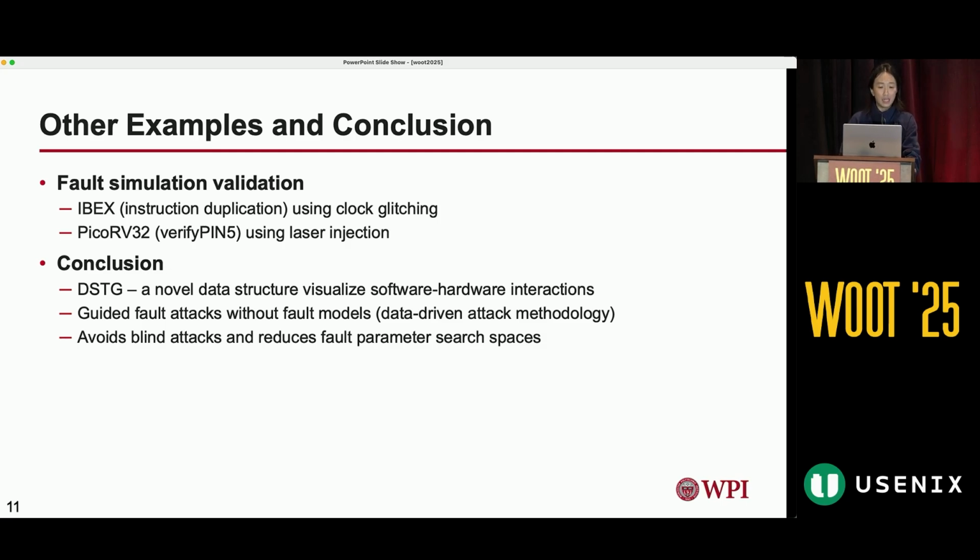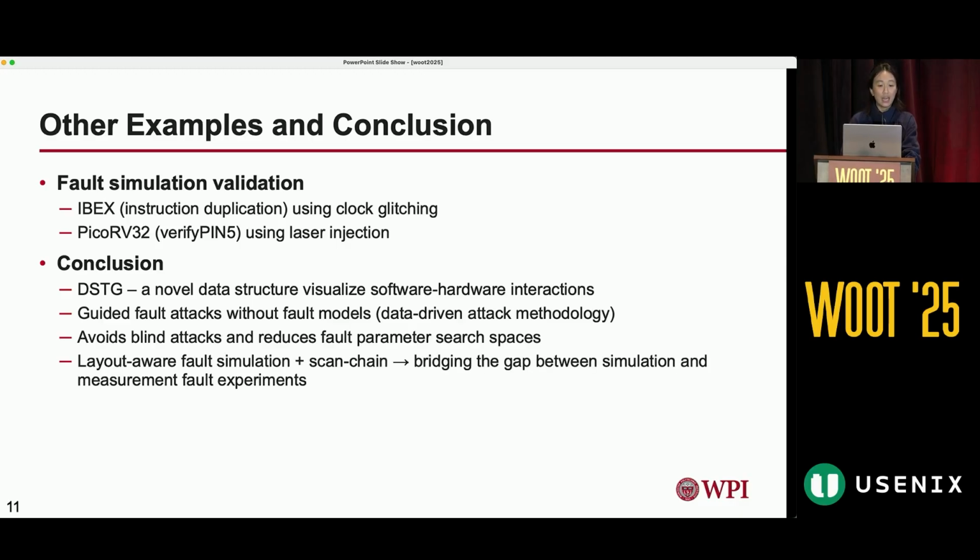By having this guided attack, we avoid blind attacks and are able to have very high precision to reduce the fault parameter search space. And at the end, by incorporating layout-aware fault simulation plus scan chain, we are able to validate our simulated results with measurements from the fault experiments.